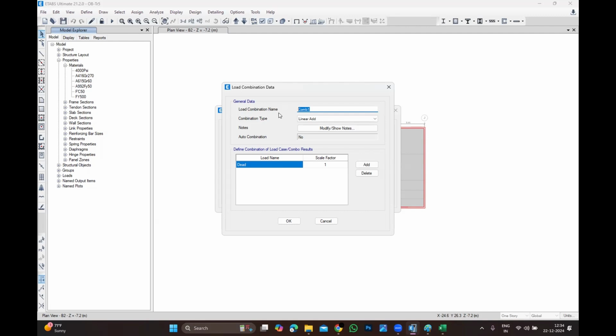I'm not going to check the serviceability case on this model. But if we check the serviceability case on the other model, 100% sure it will be safe, because you already increased your moment of inertia. By reducing 30% and now using 100% of the moment of inertia, it will definitely pass, because a 30% difference will be there in the column. You're getting the point.